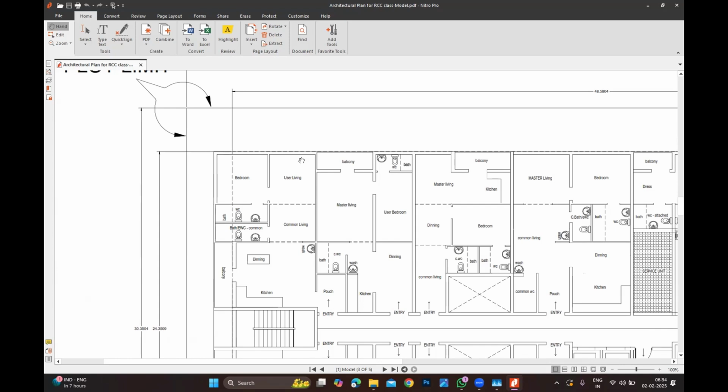If you try to place the opening closer to the vertical elements, either closer to the columns, okay, bigger opening I'm talking about, maybe 1 meter by 1 meter, 1.5 by 1.5 meters, or closer to the shear wall, closer to the core wall, what happens? You don't have any kind of stiffness, because in another case you do have a staircase base slab thickness. If you don't have stiffness here, then the wall's out of plane moment will be more when compared to the in plane moment.